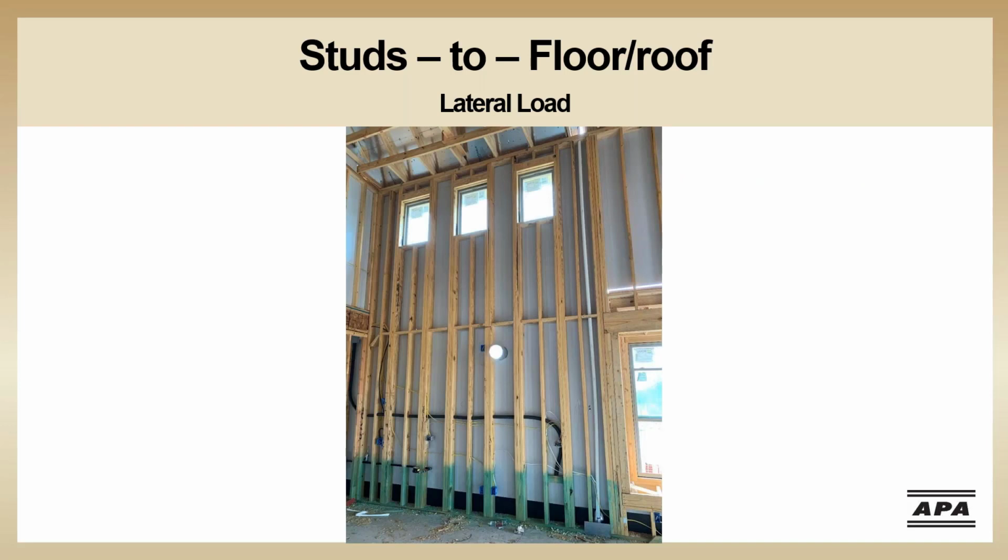In this photo of a tall wall, the studs span from the first floor all the way up to the roof, with a row of blocking at the midpoint of the wall. Engineered wood studs are ideal for this application because of their strength, straightness, and dimensional stability.